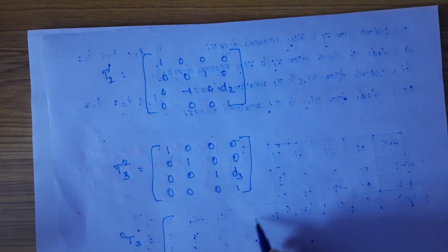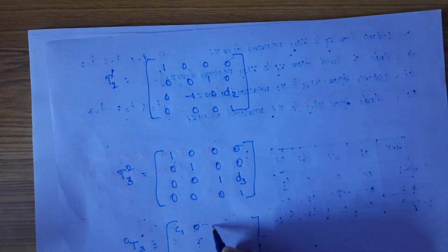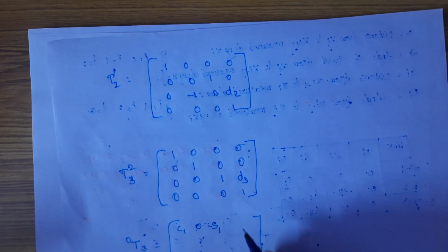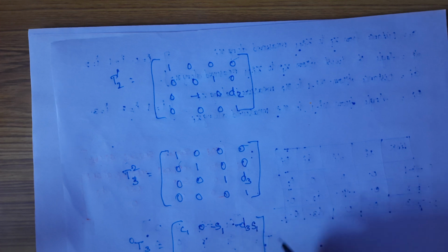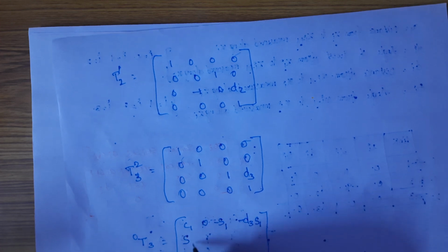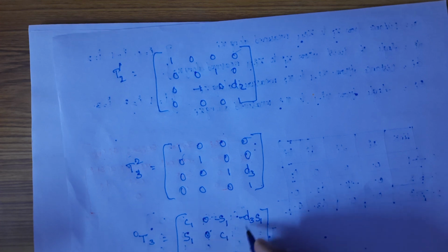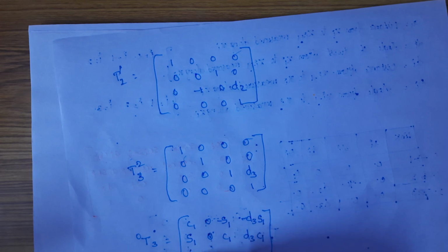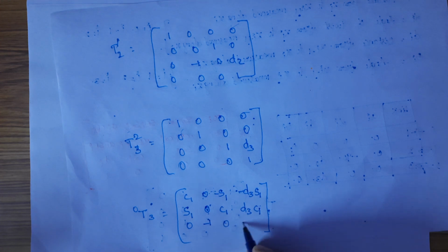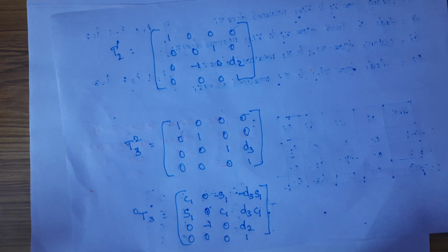I have got an answer of cos theta 1, 0, sin theta 1, minus d3 sin theta 1; sin theta 1, 0, cos theta 1, d3 cos theta 1; 0, minus 1, 0, d2; 0, 0, 0, 1.